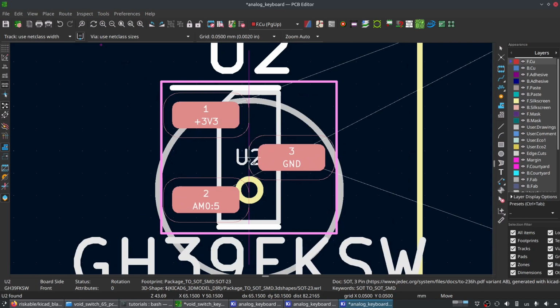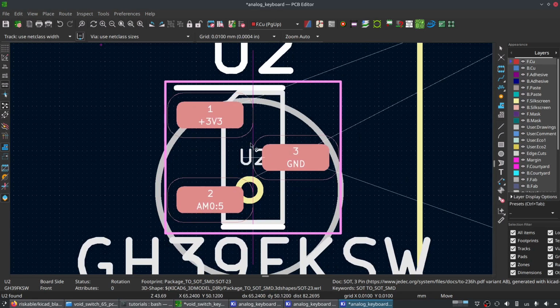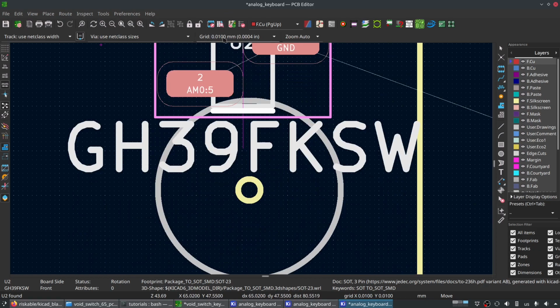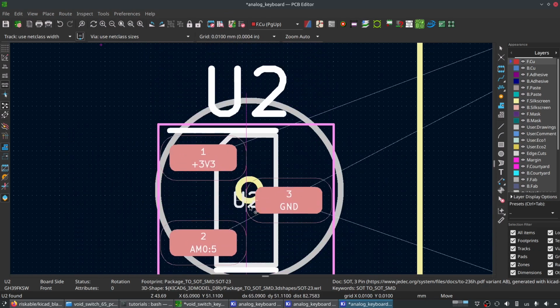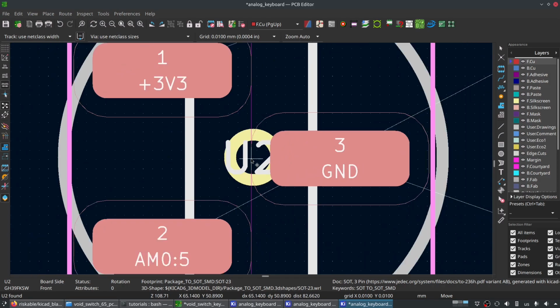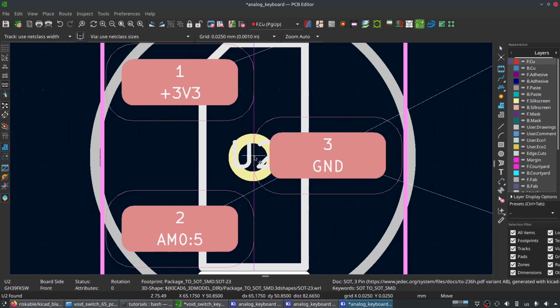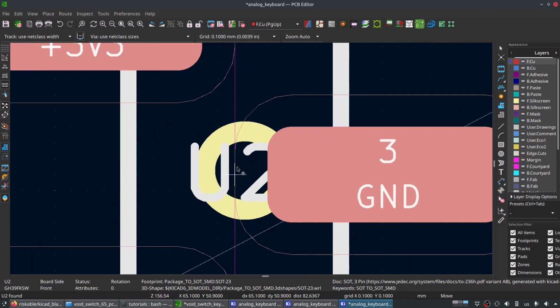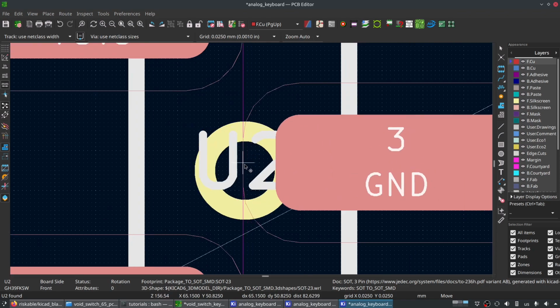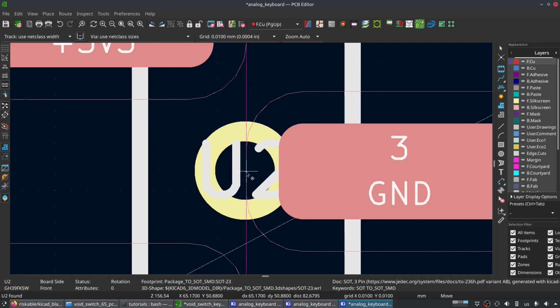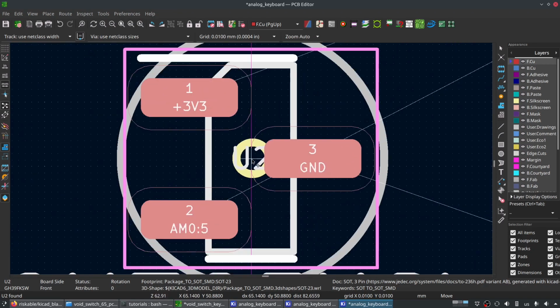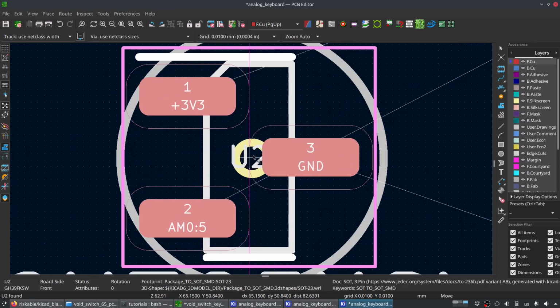Just a smidge is all you need. So let's say I'm all the way in my user grid. If I just hit Shift N once, I've got, I don't know if you can see that, 0.01. You probably don't need to get to that level of fine detail. So I usually go back a little, like 0.1. No, that's not enough. 0.25, that's probably enough. Nope, apparently we do need 0.1. So we want to zoom out a little bit so we can see the crosshair.